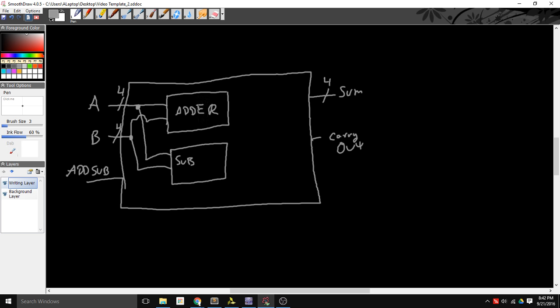So literally what's happening is that whatever my inputs of A and B are, they are being added up here and they're being subtracted here simultaneously, because these things are working in parallel. They don't rely on one another. They're just hardware, different circuits altogether. And I only want to forward my outputs from each of these things to my LEDs based on what operation I'm doing.